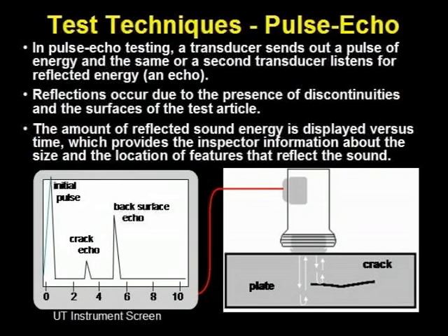The pulse repetition rate can usually be set fairly high, a few thousand pulses per second, because the velocity of sound in liquids and solids is relatively fast. The pulse repetition rate limit is set by the round-trip travel time for all the internal echoes. The next pulse should not be sent out if it would interfere with echoes which are still occurring. Otherwise, interpretation of the A scan becomes difficult.